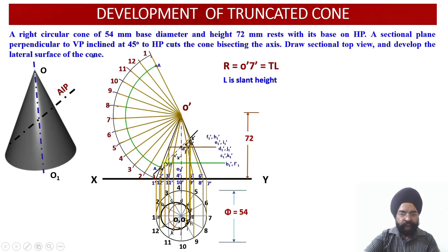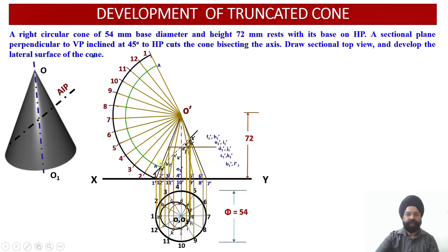So what has to be done? From the apparent length point, draw the horizontal locus line up to the true length, either on this side, here again the true length is available, or on the other side. Now I will be measuring this distance, which will be half a millimeter to 1 millimeter higher than this distance of O dash L dash and O dash B dash over there. So I am going to draw an arc corresponding to this length, O dash B1 dash or O dash L1 dash. Now, what we have done over here, we have marked the apparent length onto the true length.